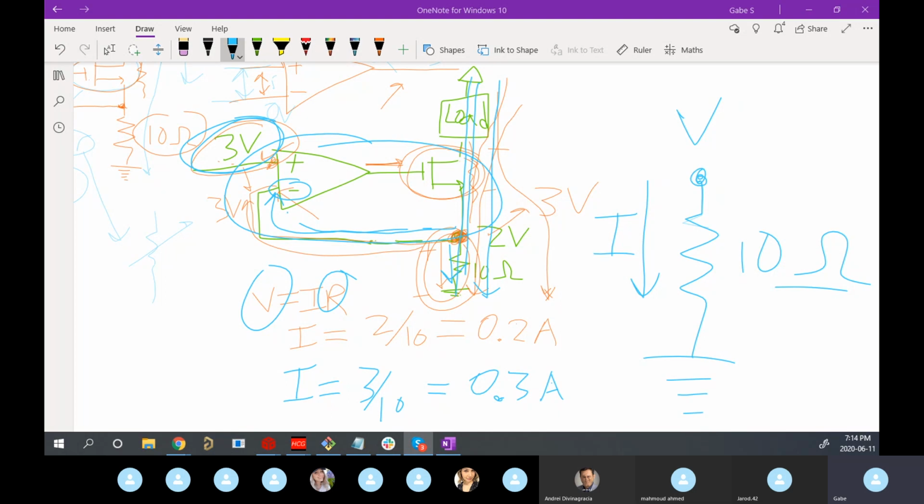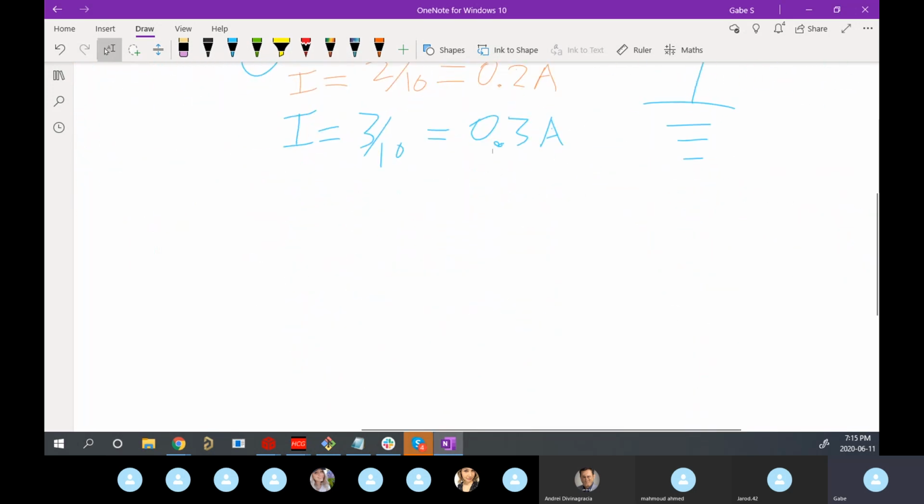And so we put this circuit in a little PCB that fits in the headset on your head and puts current through your skull. TMS is a great question. It's not TMS. It was actually something called TDCS. So it's transcranial direct current stimulation. So you actually had electrodes pasted to your head and current flowing through your brain. TMS is transcranial magnetic stimulation, and so those use magnetic fields to generate current, so no actual direct contact. But you can imagine, so same circuit, right? I control the voltage.